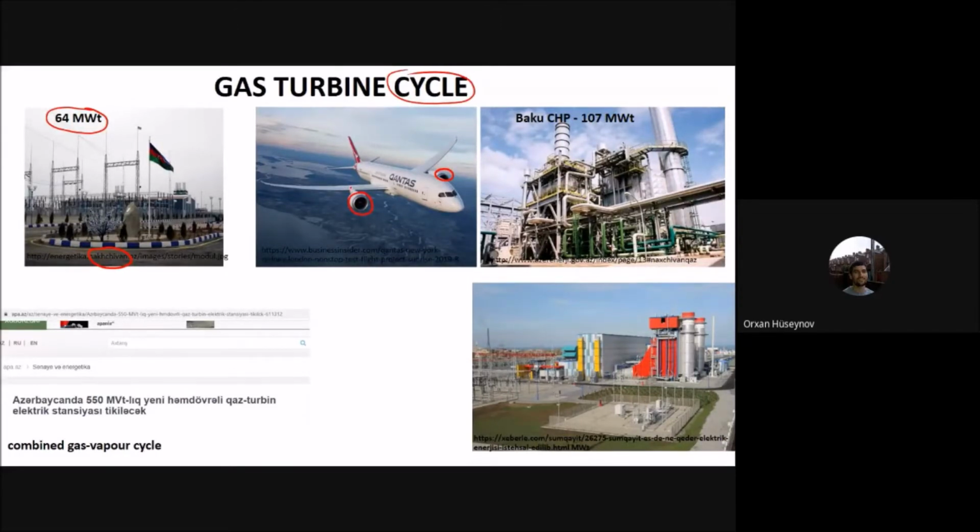Modification means that here you have a nozzle. In the real gas turbine cycle you don't have the nozzle, but you are adding a nozzle for the higher momentum that is needed to propel the aircraft. You can also have different modifications, like a propeller, an expander, a diffuser, or you may not have any of it. It depends on the configuration, but you have slight modifications to the gas turbine cycle. You should know that this is the gas turbine cycle used for airplanes.